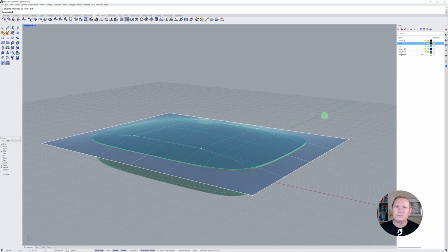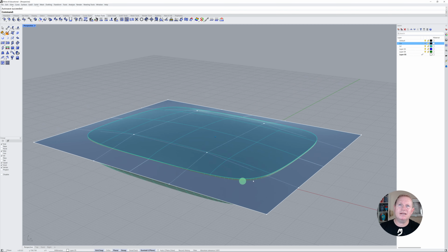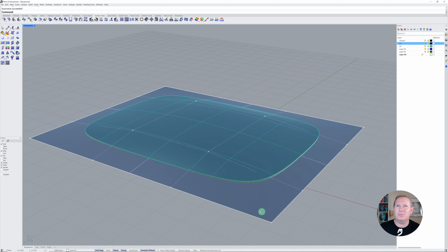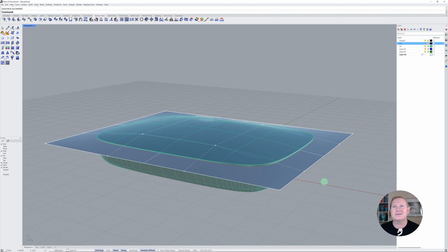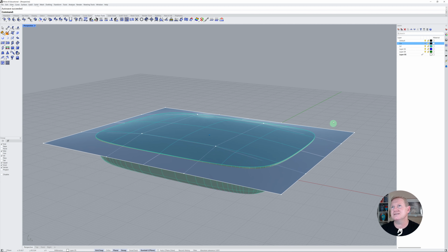Okay. So this strategy is a much better strategy because it's a perfect square grid. When we do a UV divide in Grasshopper, we're able to control our grid. With the curved one, I think it's going to curve the UV divisions, and I think we want straight UV division. So this will probably help. So let's just use this surface instead.